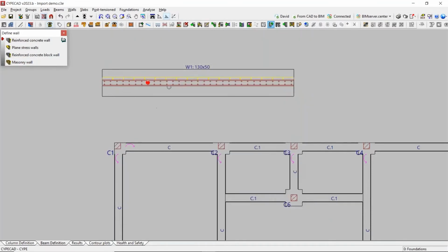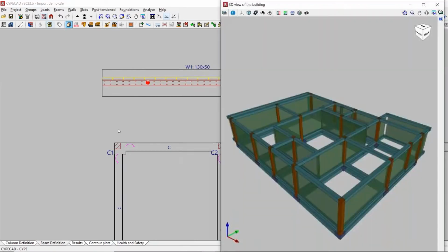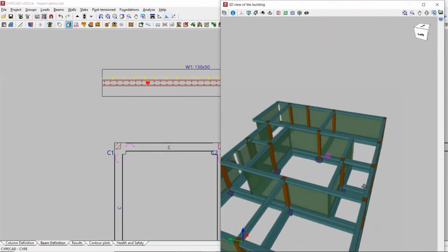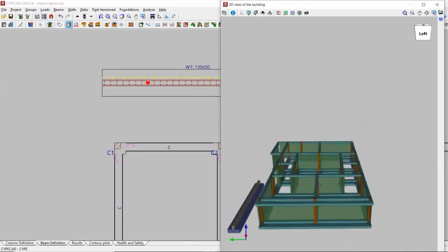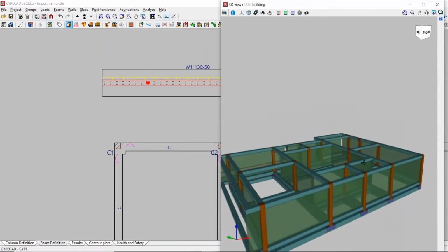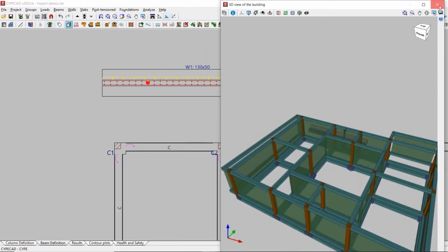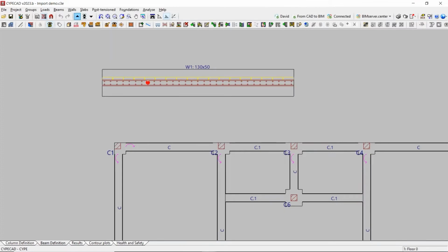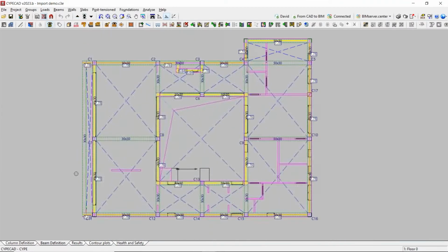And now that we're talking about panels, I'm sure that you've noticed that now we are only missing the panel information that we are designing here in CYPE. So let's go to the upper floor here on this level. And you will see that by default, we have imported all the different panels as empty spots here as openings, and we can turn this into panels with the help of the panel manager.